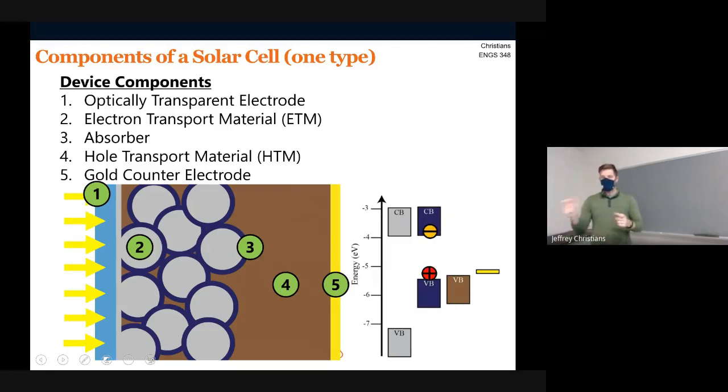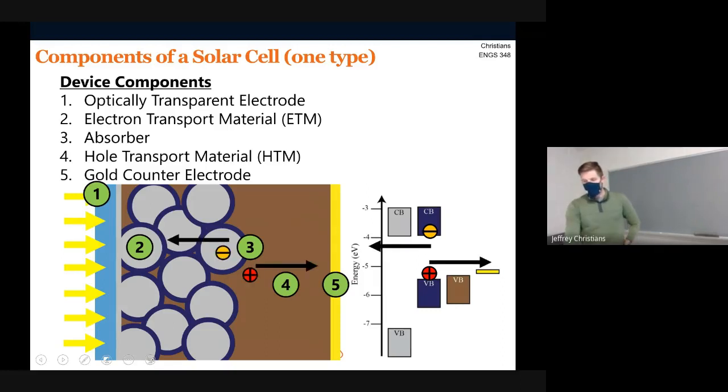In your blue layer, that's where you actually get what we call charge separation, where you absorb light and give something extra energy. Then you can separate it out into different materials, and that's how you trick it. Instead of them coming back together, you can separate them out into 2 distinct materials and get charge separation that way. One material directs it to the positive electrode. In one material, it goes to the negative electrode.